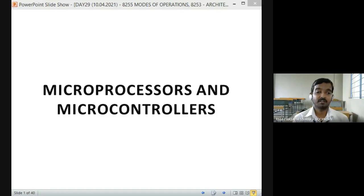Thank you Karthikeyan. A, B, C are the 3 ports. These 3 ports are organized as 2 groups of control. Yes, port A, entire port A pins, 8 pins, plus port C upper 4 pins, are under the control of group A. The remaining pins are under the control of group B. Among these 3 ports, which port can be used as two 4-bit ports also?